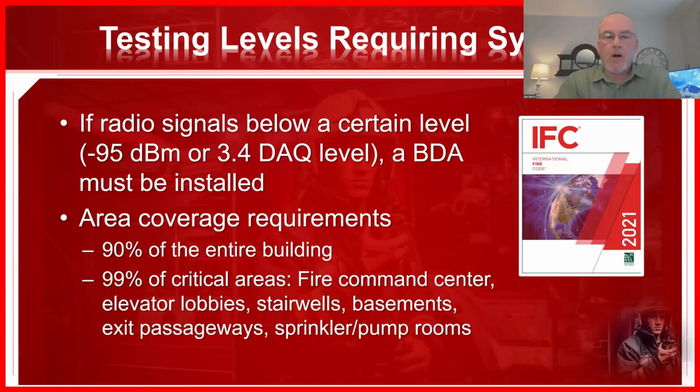All right. And what it requires is that for these tests, 90% of the entire building has to have sufficient coverage, whichever test you're using. All right. And 99% of critical areas. So basically areas where people are going to try and get out or where first responders are going to be doing what they need to do.